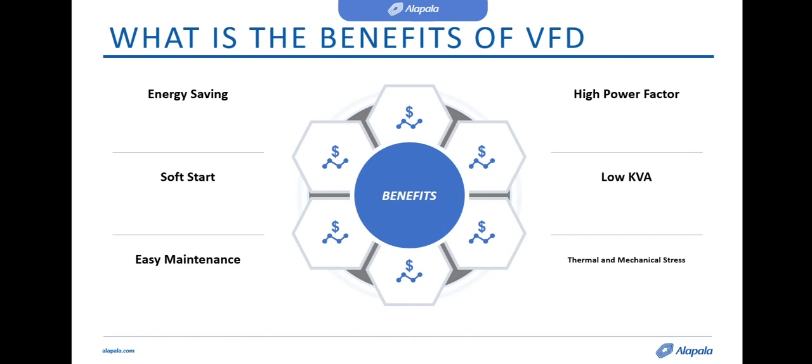You can see here the 6 impressive benefits, and the first one is the energy saving. Variable frequency drives allow you to consume less energy than other speed control techniques when load requirements are less than full speed. Okay? And when we take a look, the other benefits are the soft start, easy maintenance, thermal and mechanical stress.